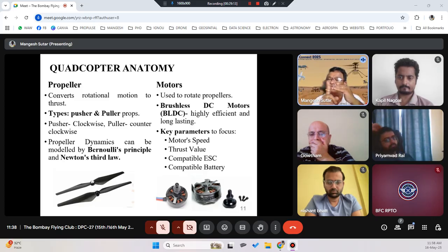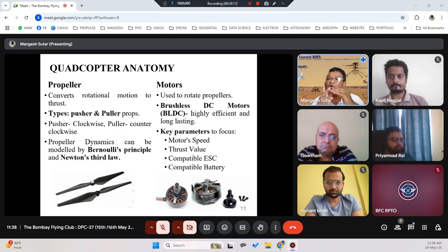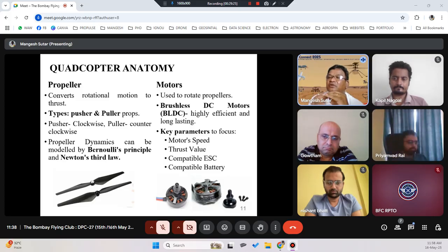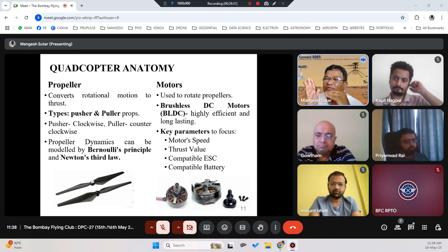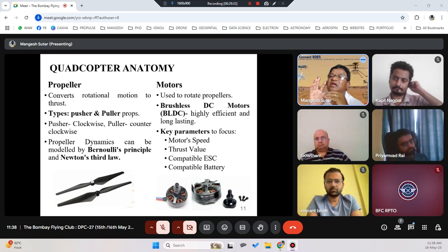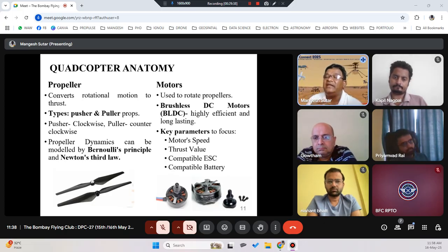You will see a lot of times sparks would happen in the motors also. To prevent sparks, they were using carbon contacts. But eventually the carbon wears out because of the friction, so every 6 months or 1 year, you have to change your carbon brushes. And because of the friction from the touching, the efficiency of the motor was not good, and that's how the innovators designed a different type of motor.